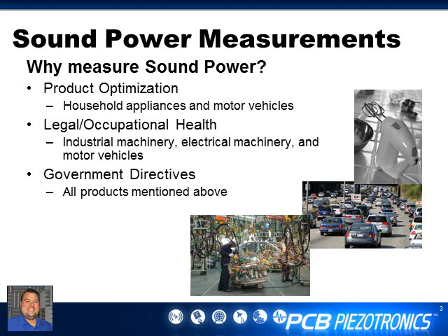Another big reason is legal or occupational health. If you're continuously working with a particular machine, or if you have people working with this machine, you may have to verify the sound power of the machine after it's been installed, and then verify it every year to make sure that it's not exceeding a certain limit that is imposed on you by either the Occupational Standards Committee or even an employer or the government.